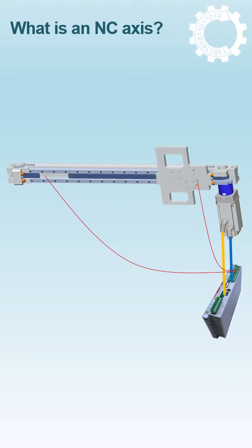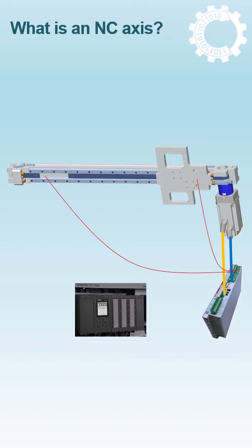Now, all the hardware of the axis is set up and we can start controlling it. For example, using a PLC connected to the servo controller through a real-time bus system. First, we can set tighter limits on the travel path using software limit min and max values, allowing a smooth motion control of the axis. Then, we can send movement parameters and commands from the PLC to the servo controllers, and that's almost it.